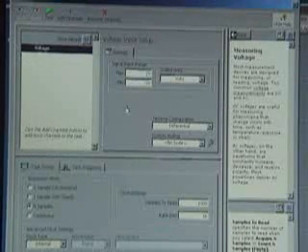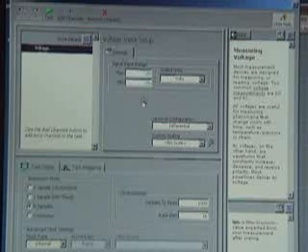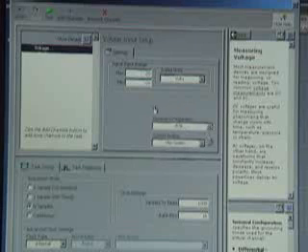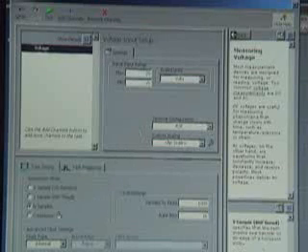Then another window comes up to change things such as the maximum and minimum voltage range that you can measure. This particular DAQ card has different modes that you can select, and how you want to specify the sampling, or if you want to trigger it, or anything like that.